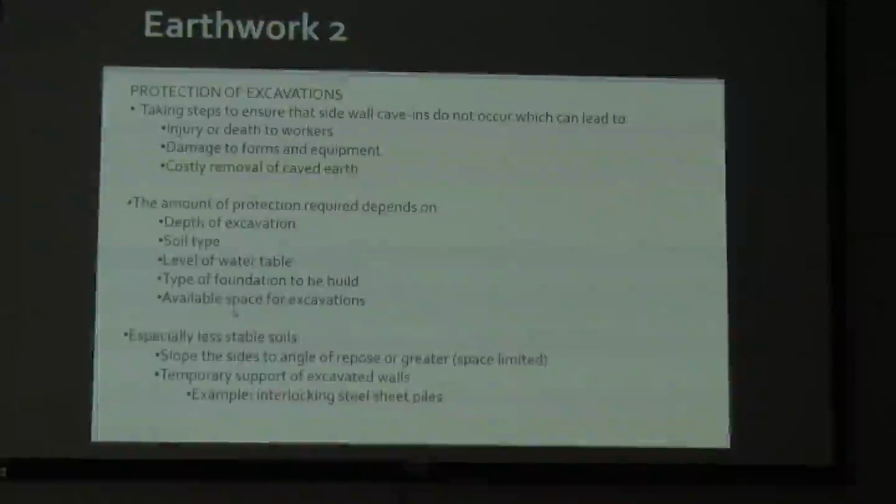available space for excavations. Especially for less stable soils, the slope, the sides to angle of repose are greater, if space is limited. So we have less stable soils, we of course want to have a much lower rise over run, or vertical over horizontal slope, as opposed to one where we can have maybe a 1 to 2 slope. We'd want something much smaller if we have less stable soils.